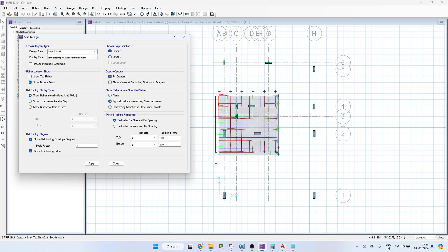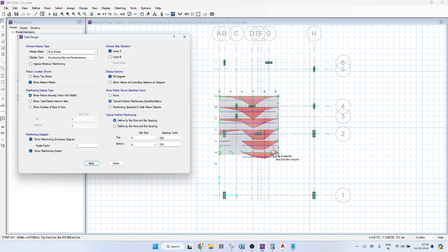We'll next focus on the bottom bar. Bottom bar, see, 900 and all it is asking. It requires 900 square mm per meter. So you can't go with 8. You can reduce 8's spacing to 150, then it will say it is requiring still more. 100, maximum is 150. 100 and all, like 4 inches spacing, is difficult. So going to 10 also won't be possible. It will show like this only. 12, if you show also.